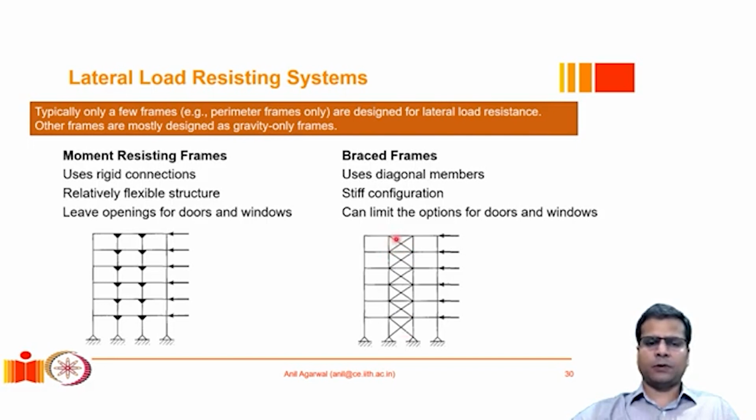One we had seen before was basically a chevron kind of brace, where the two braces were meeting in the middle of the beam. There can be another variety wherein you may have a single brace on each side and two bays may be covered. This is kind of an X bracing. For most of the lateral load resisting applications, we avoid any K type of bracing wherein the braces meet in the middle of the column. It is okay to meet at the middle of the beam because the beam is not such a critical member for the overall stability of the structure, but having braces meeting at the middle of the column is strictly prohibited